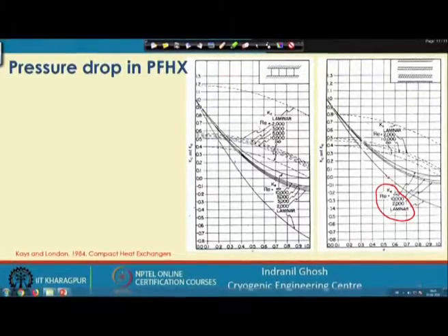For different Re values we have different Ke and Kc. Not only do we have sigma on this side, we have the Ke, Kc values for different Re, depending on whether it is laminar or very turbulent, where Re is infinite. So, between this limit we have the values of Ke and Kc.